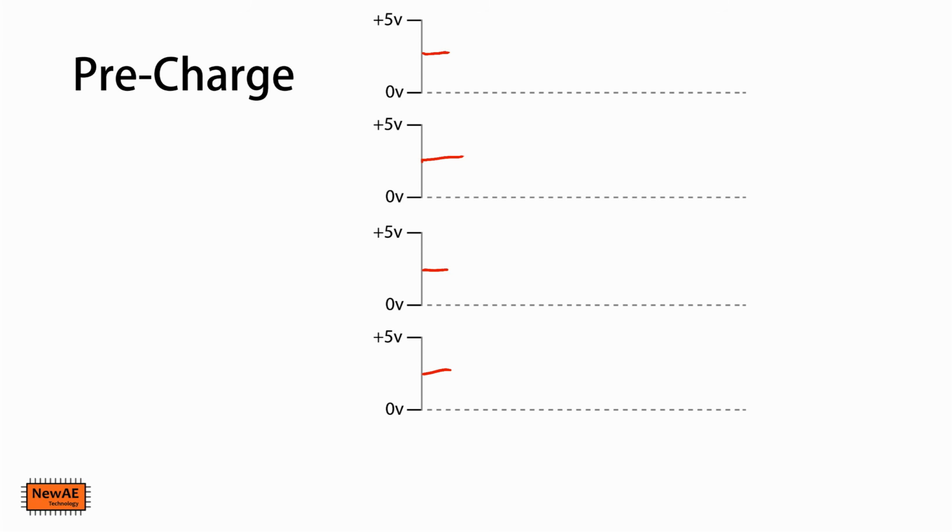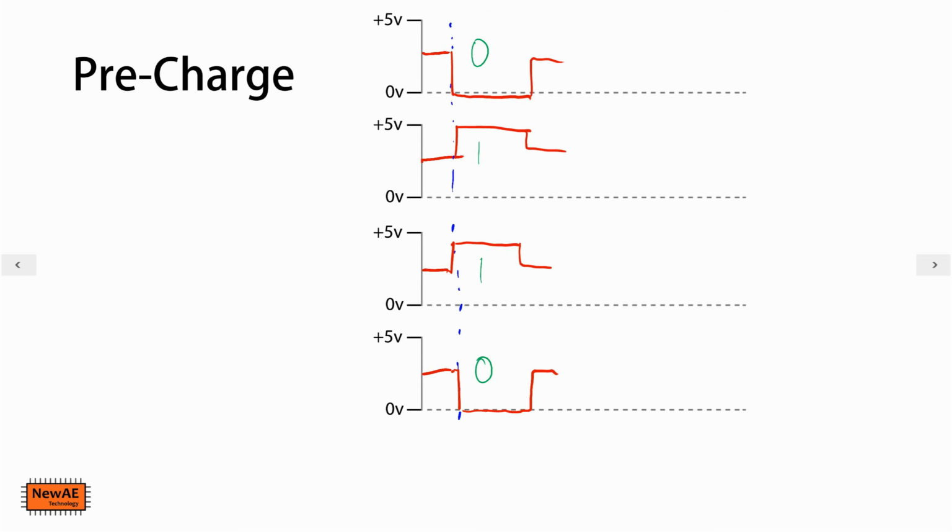But what does it mean for us as attackers? Let's say we had the same thing, 0, 1, 1, 0. What's going to happen now is the microcontroller, at the clock cycle, so let's draw our clock cycle in here, is now going to take those lines to the final state. In reality, it may want them to be valid slightly before that clock cycle, but we don't really care for our purposes. So it uses that data, and then it puts the lines back to the pre-charge state in anticipation of the next clock cycle. So we put them back to pre-charge, and we draw where our next clock cycle will be.